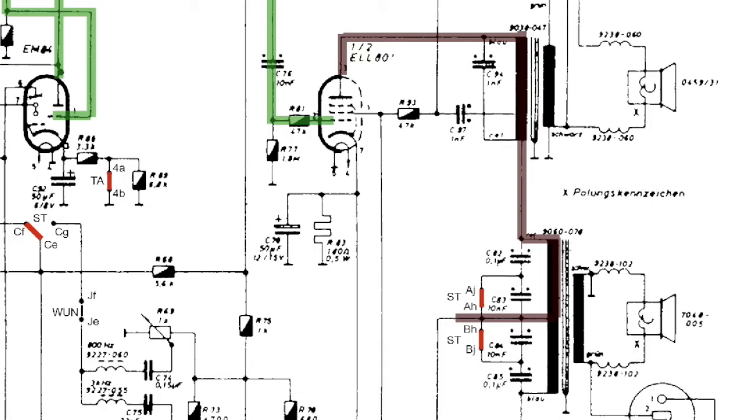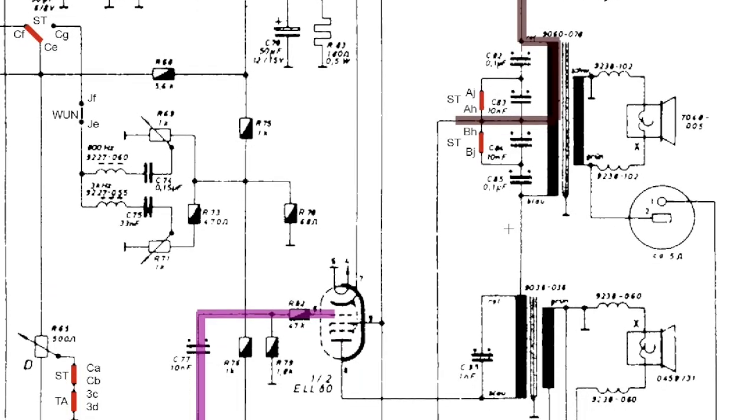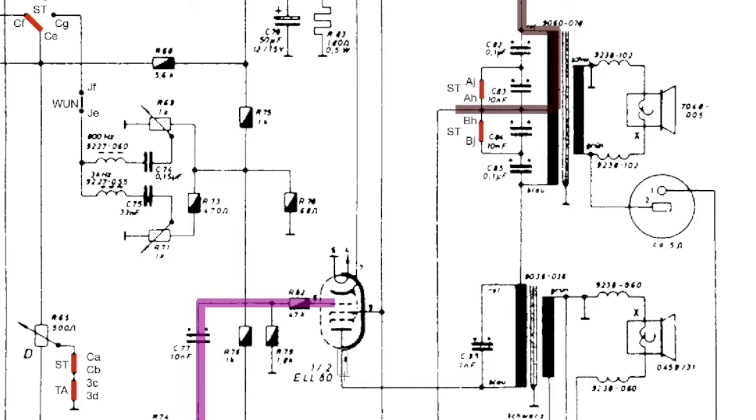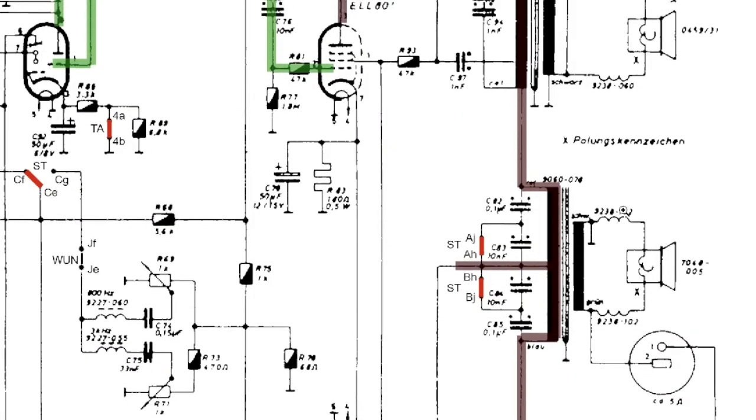At the same time, if you remember, we have the exact same bass frequencies on the other side because they were summed in the beginning. However, they're on the other side but inverted. So this pentode is driving the opposite cycle through this half. So what we've got here is a typical push-pull amplifier. However, the push-pull is only for bass frequencies. So this pentode and that pentode are driving one transformer, the bass speaker transformer. Bass frequencies, push-pull. Now the high frequencies are different.